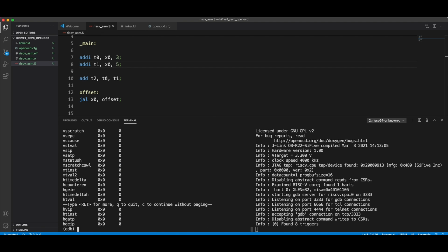So that's how you can debug and test your code using OpenOCD, and it's very powerful when you develop a driver or low-level code where you don't even have stdout or printouts ready. At that level, if you want to debug or write code, this is very useful. But it comes with the cost that you should know a couple of GDB commands and how this entire thing works. Otherwise, you might find it difficult.